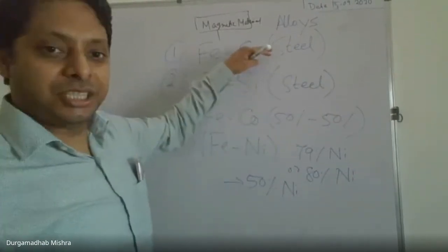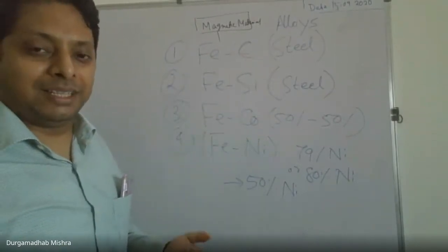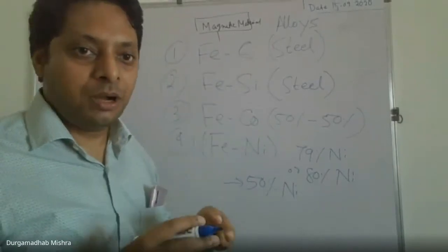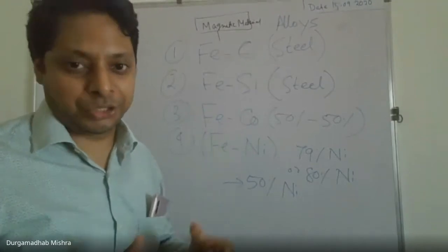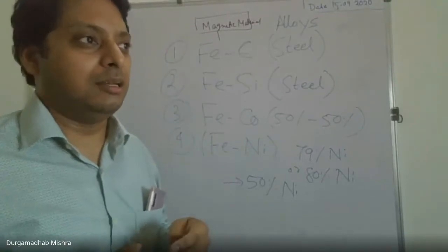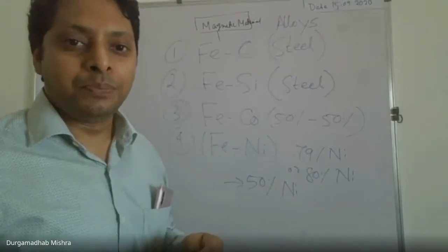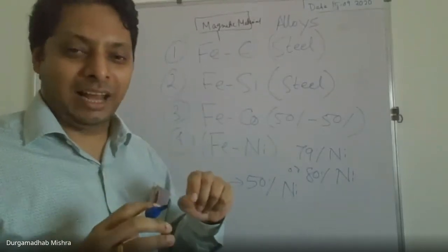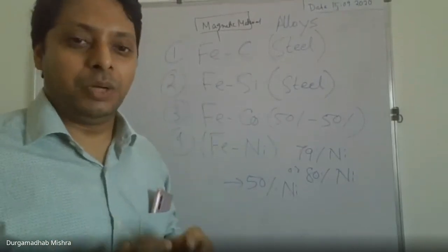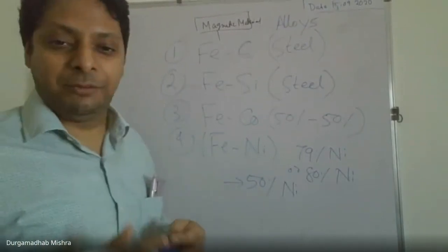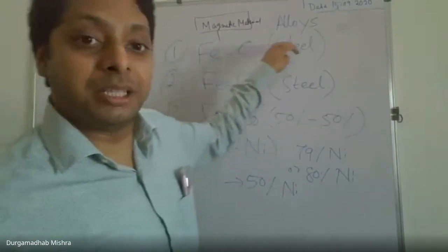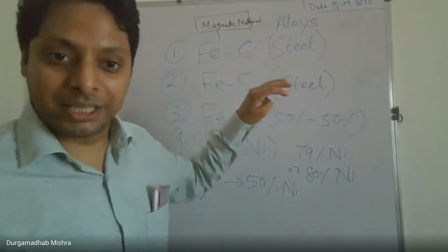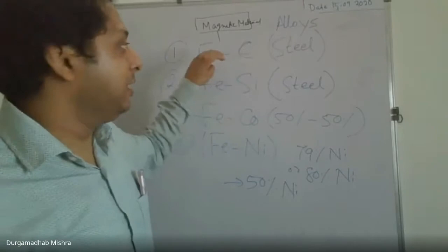So one thing is you are looking at the magnetic properties. Okay, so for a soft magnetic material, what we need is a low coercivity and high permeability. So that is the first thing. But then you also have to look at the mechanical properties, the stress, so how much stress it gets. Okay, so if you have more stress or more defects, that is going to affect your magnetic properties as well. These little things can maybe be neglected in the beginning, but when you are making a real product, you cannot neglect the defects and impurities. So that's why you have to add some other impurities deliberately. It is not unnecessary. It is deliberate. You want to add these impurities so that you can improve some other properties. Okay.